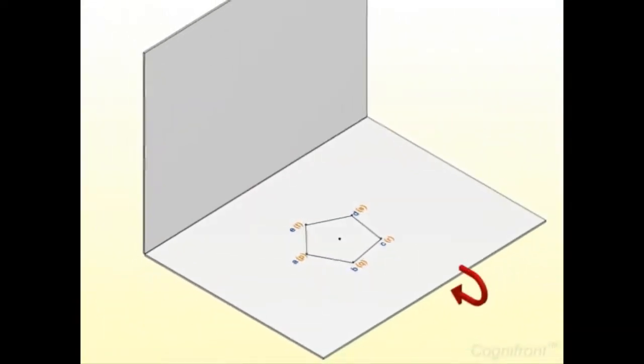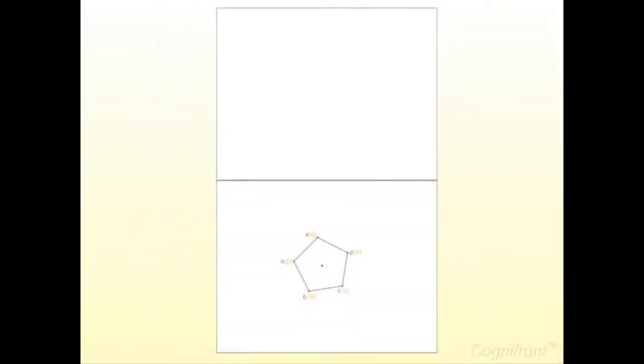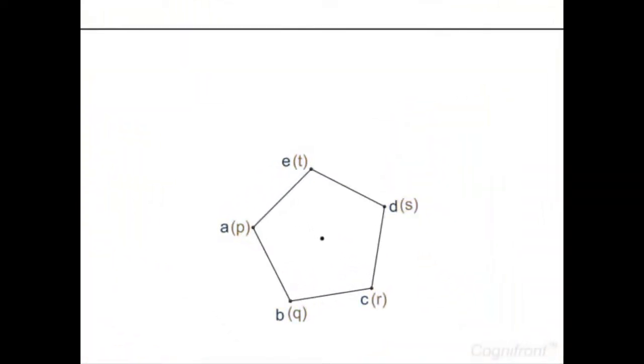Let's draw its projections. For this, first draw a horizontal reference line XY. Below the line XY, we'll draw the top view, which is a pentagon with side 50 mm. Observe that top face A, B, C, D, E is visible and base P, Q, R, S, T hidden. The side EA makes an angle of 45 degrees with the line XY.